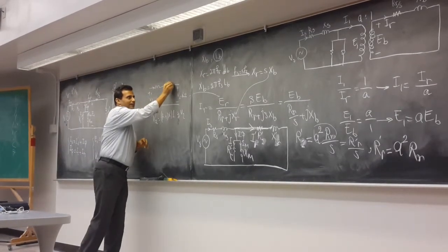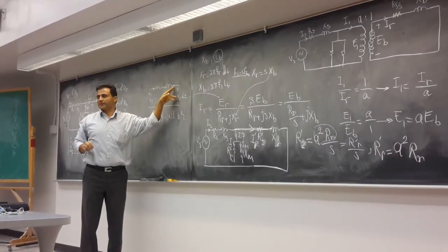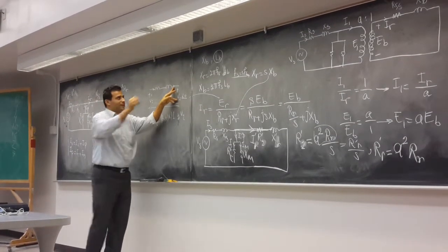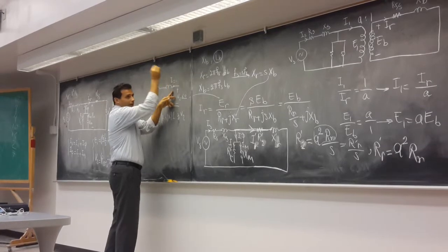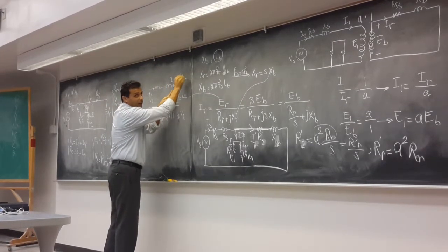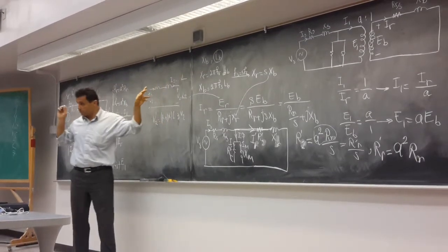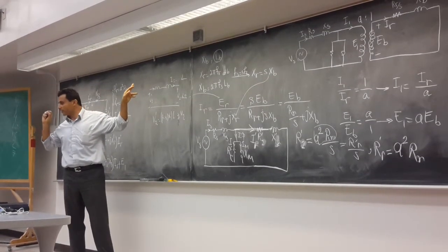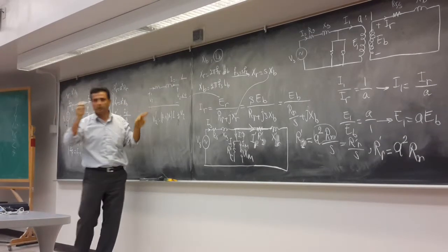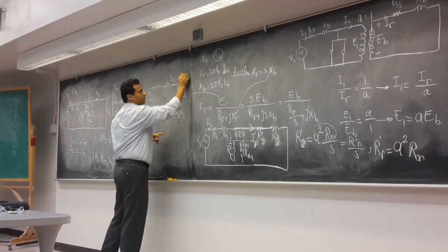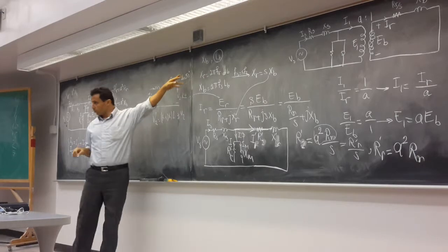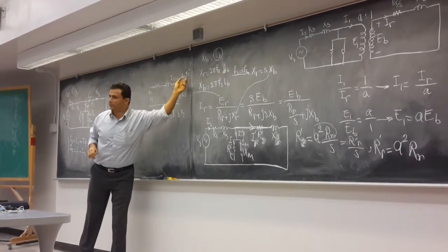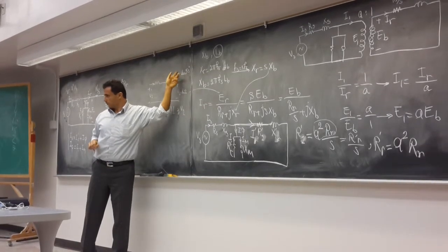We said in the exam the load is 0.6 lagging power factor. So basically this current is going to be something with lagging. We said lagging. The reason I'm saying it is because nobody did it. Only one person in the class did that one. We are saying lagging power factor, minus 53 degrees. Go check your papers now. I'm going to give it to you. See how many of you did this one. Minus 53, lagging power factor.